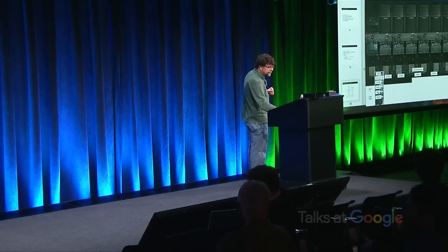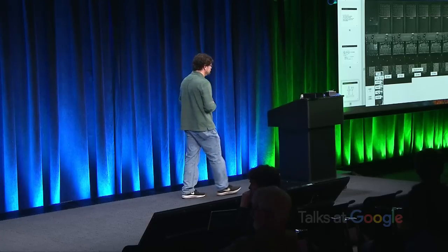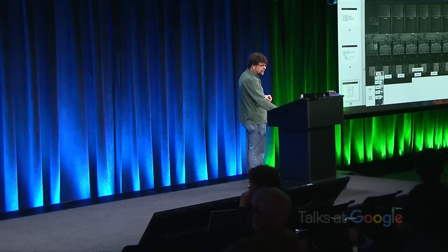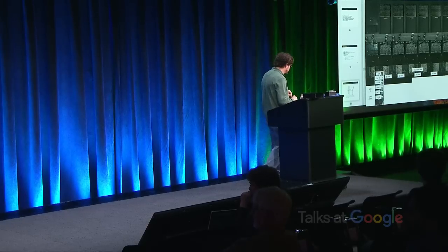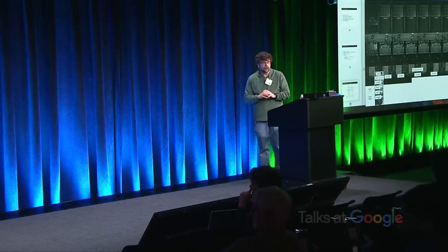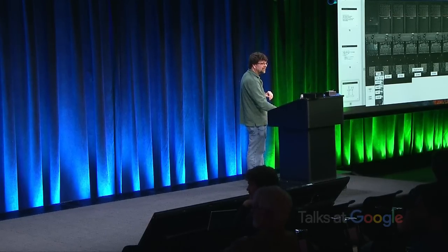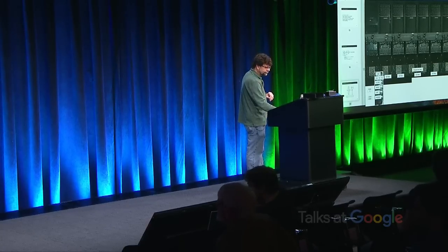So initially I'll hit the initialize button, which sends out a pulse that is meant to start the first stage of the computation. And in this case, the first stages are loading some values in. Now if you look carefully, the first accumulator, that second panel here, now has a couple of values in it that weren't there before. The first digit is moved up 1 place, and this next digit over here is moved up 5. So we've stored the number 15 in this accumulator.